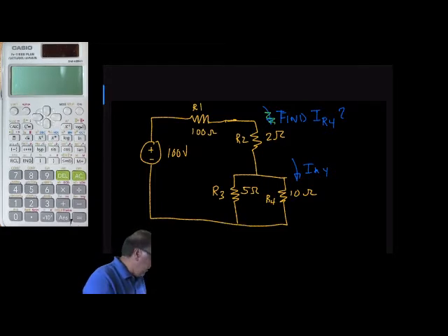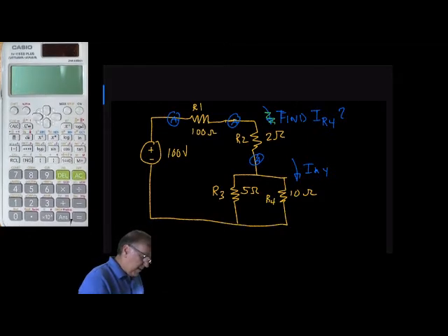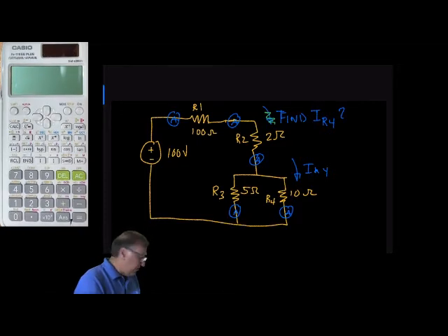If we inserted 3 ammeters here, here, and here, the current through this path would be the same because it's in series. However, if we inserted an ammeter at R3 and R4, they would be different. However, the sum of those two would equal any of the other ammeters in the series circuit. We could then calculate the current through the circuit by calculating the total resistance of the circuit and then use Ohm's law.